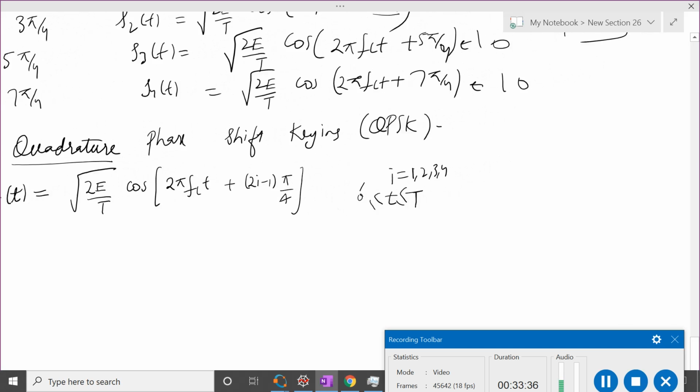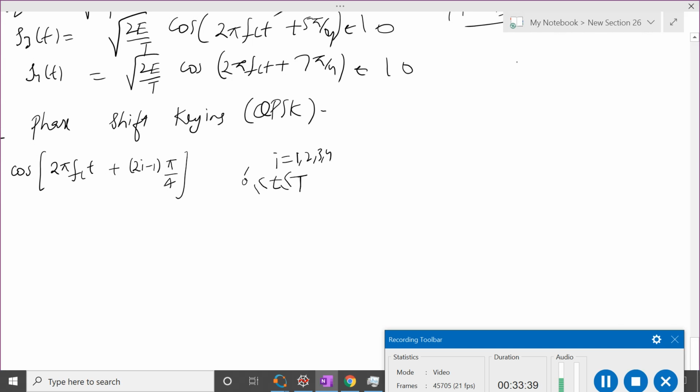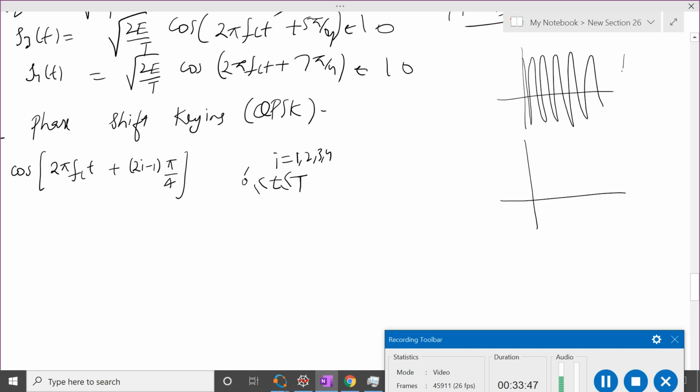Before I move forward, let me make a pause here. For BPSK, the high frequency signal is supposed to be this, right? Then if you have suppose 1 0 1 1, how will it be represented as a waveform? So this is the time interval Tb. 1 means for this time interval you have a signal with 0 phase like this. Then you have a 0, so its phase will be something like this. Then you have a 1, so it means it will start from this.